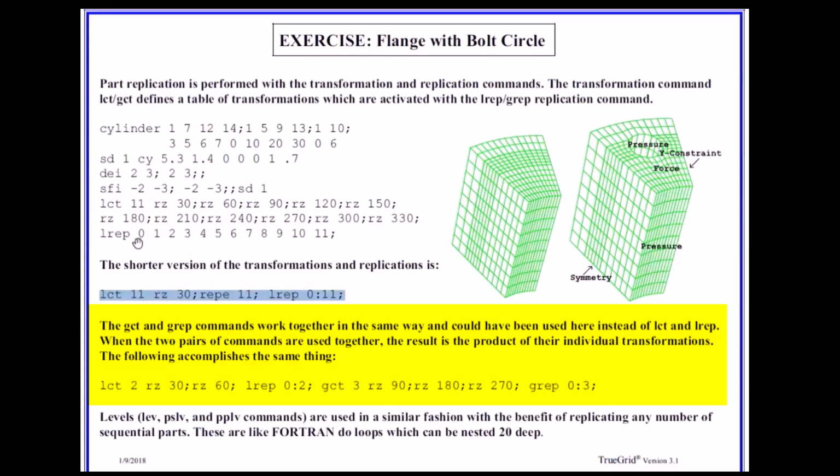So for example, if the global had 5 transformations, suppose you made 5 different movements or a change in coordinates. So you've got 5 of these objects. Internally it takes the product of these. So if you have 5 in the global and 12 in the local, you're going to get 60 copies. Very powerful. You can do lots of replications in a very easy way.